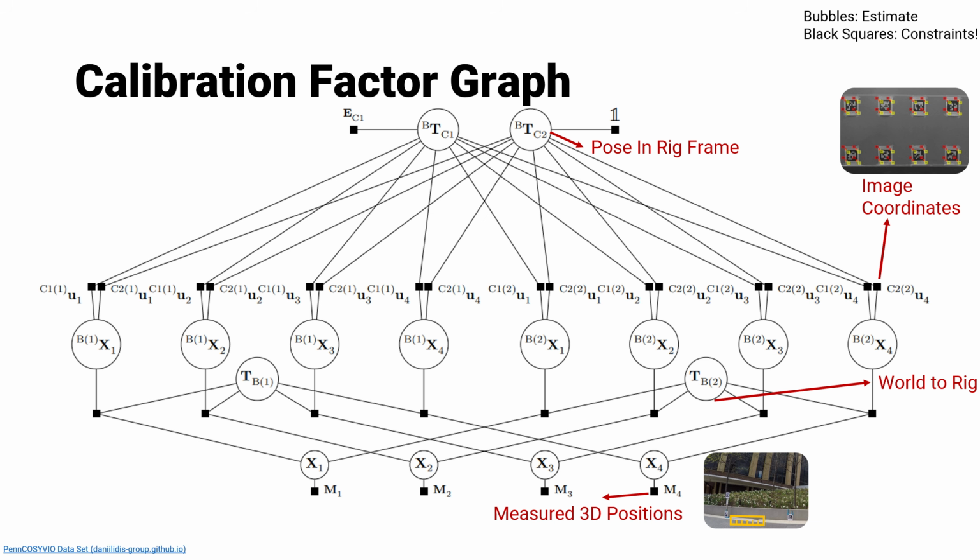We modeled that into the frame, unlike how standard calibration procedures are. In standard calibration procedures, the world frame coordinates are obtained and they are assumed to be perfect. In this particular case, that was also a free variable, which we accounted for. So doing all this, we could basically obtain a calibration which estimated the errors, taking into account the error of the calibration as well. So we got this, and then we estimated the true 3D world positions of the calibration target as well.